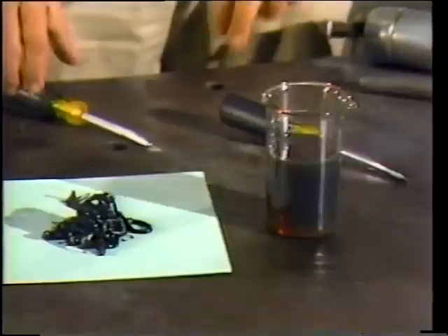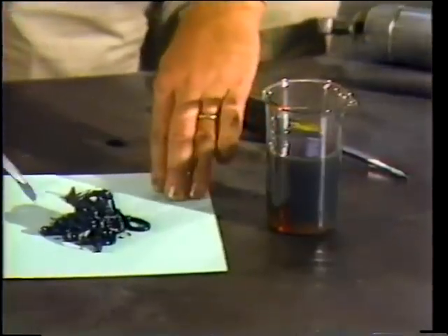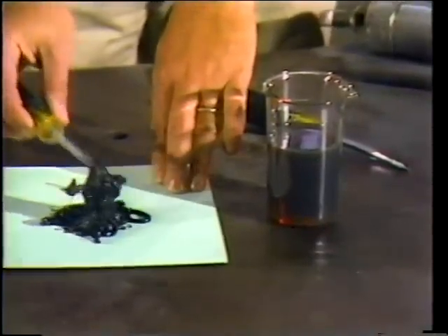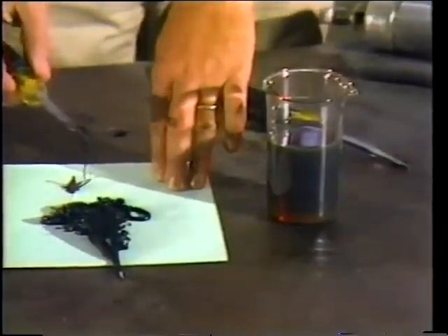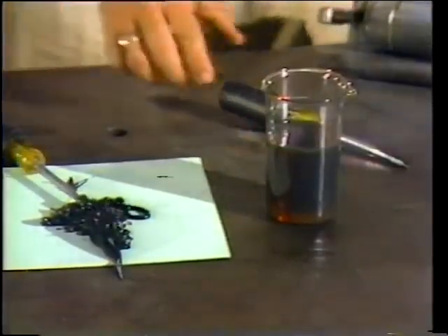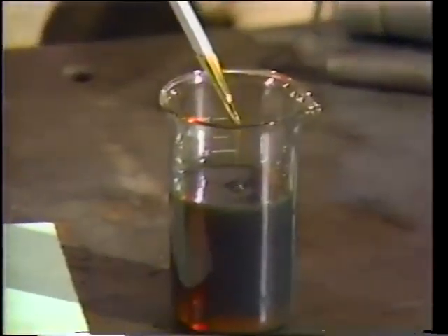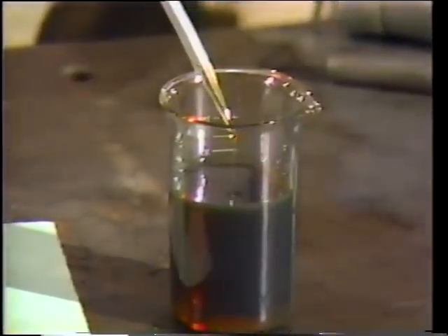A grease whose consistency is properly chosen for its operating conditions is easier than oil to keep between lubricated surfaces. Now, as long as grease remains semi-solid, it tends to stay where it is placed. Now, liquid oil is much more likely to flow away from where it is needed. Under conditions when both oil and grease